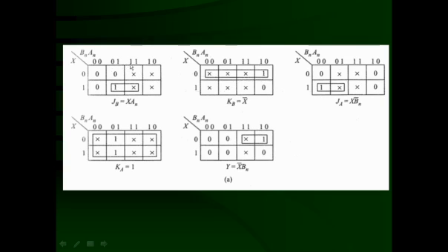Now this is location 6, 1, 1, 0 and 1, 1, 1, where these inputs are not going to occur. This condition never occurs, so you can substitute X here. So that way the Karnaugh map is prepared for JB. Similarly, it can be prepared for KB also.